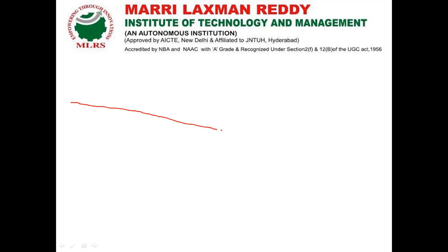We already know that this is a continuous sloping ground. This is our first point, that is the benchmark point, which has a height of 80.750. This is point number 1.